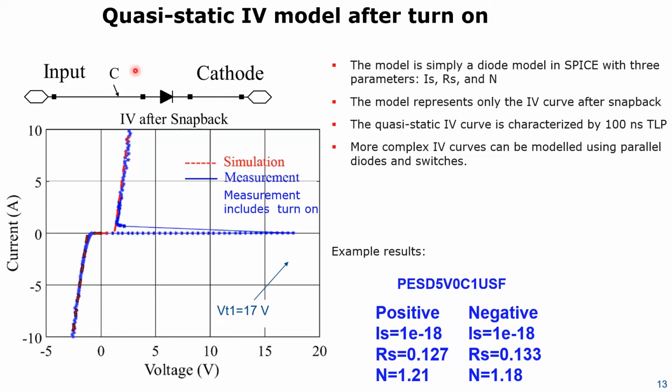And if we just take the IV curve model, so not the complete model, we see the simulation doesn't capture the overshoot, but it captures the slope, the slope resistance. And here we see, for some diode, the modified SPICE parameters. You know, in SPICE, a diode is modeled by the saturation current, by the series resistance, and by, let's call it, an efficiency coefficient. By just modifying this, one can basically match the curves. Of course, in the end, we have to add the overshoot model to it.